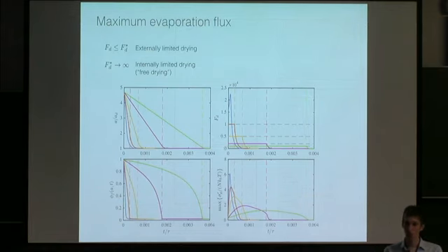And the reason that I'm not going to show you a comparison of the model with the drying, so we can do this, but the problem is that the drying rate is actually very strongly controlled by what's happening in the room where you're drying the sphere. Because obviously, ideally, the sphere will give off water at whatever rate it likes based on the chemical potential. But you have to then remove that water from the sphere. And that happens by evaporation. And evaporation doesn't necessarily happen as fast as the sphere wants it to. And so as a result, you have to choose what the evaporation rate is, which is just the maximum rate at which water can be taken away from the sphere. And as a function of what you choose, you get very different results for the drying process.